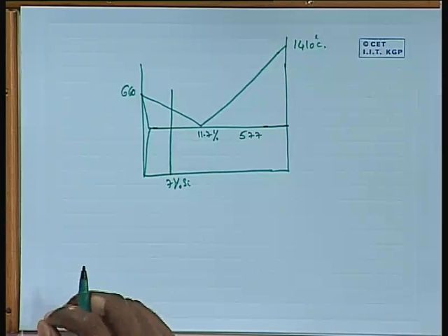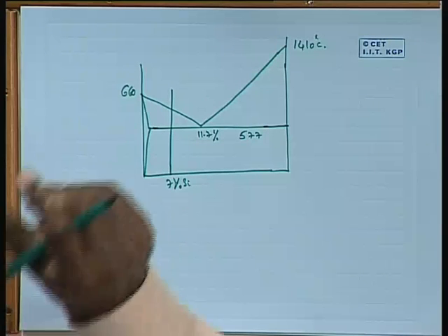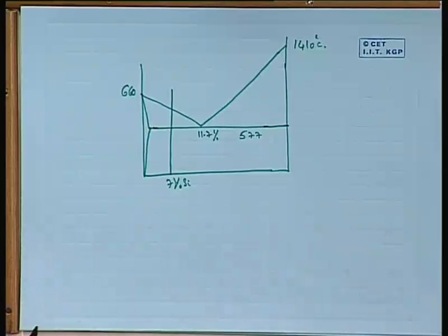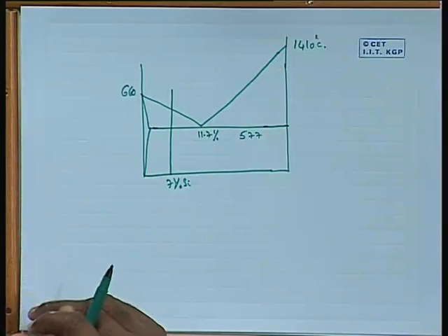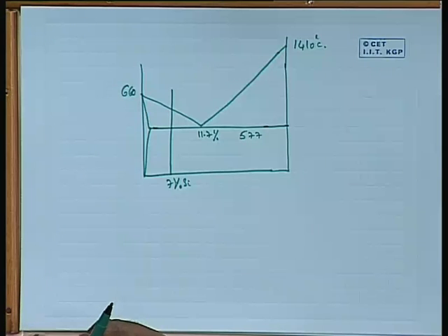When you cool the alloy very rapidly, there is not sufficient time for the silicon to grow into needles. It becomes like small particles, as if you have chopped the needles, and as a result you can have better ductility.